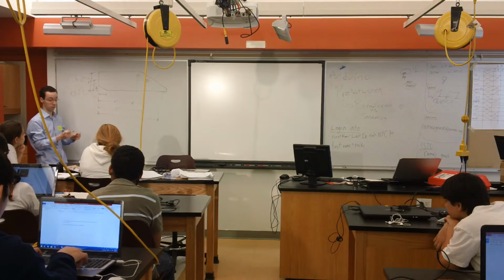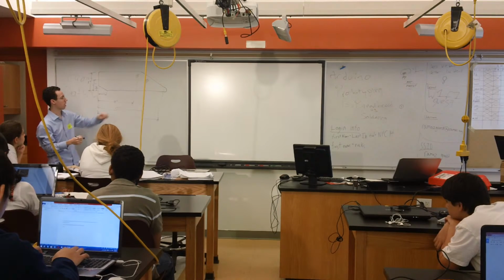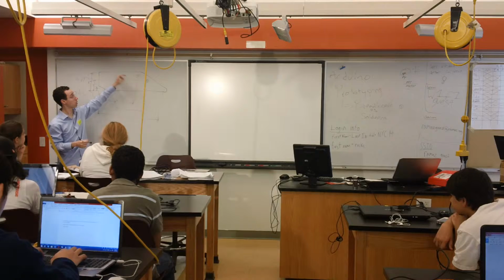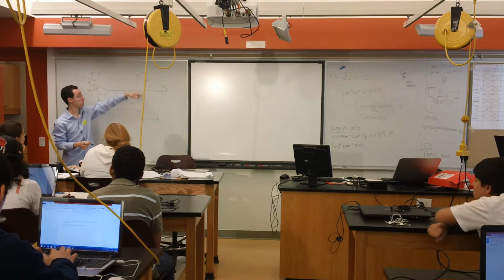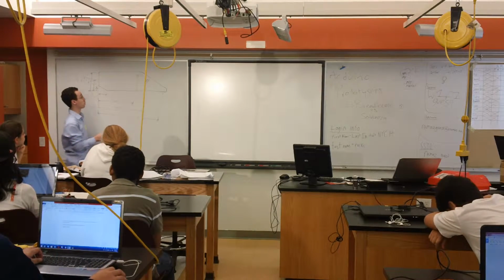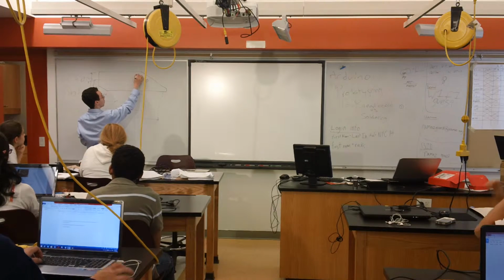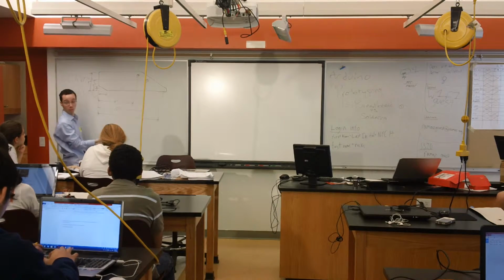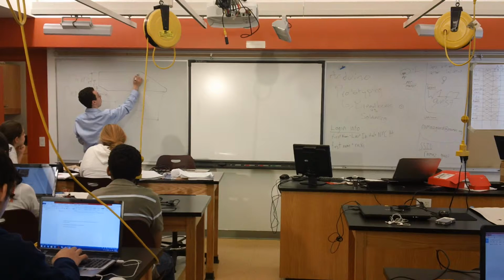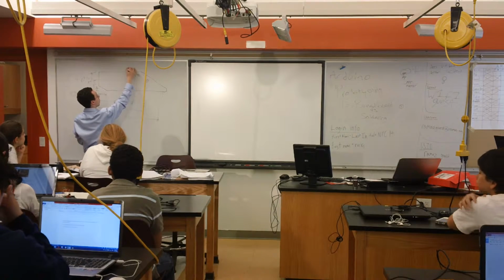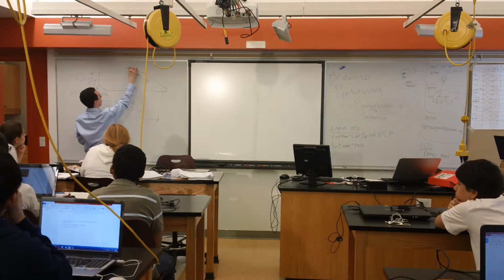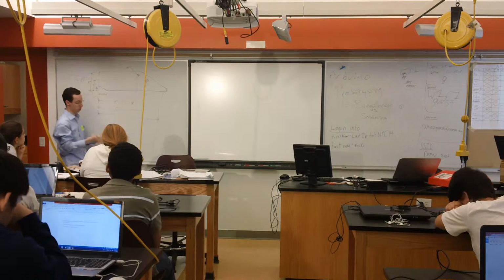So I know where everything is, but I don't know what size everything is. I haven't done that. That doesn't matter. I want to know how big this circle is, how big this radius is, and so on. So for the circle, I draw a little diameter in here, put on a leader line from it, and I say, okay, this circle has a diameter of 1 inch.